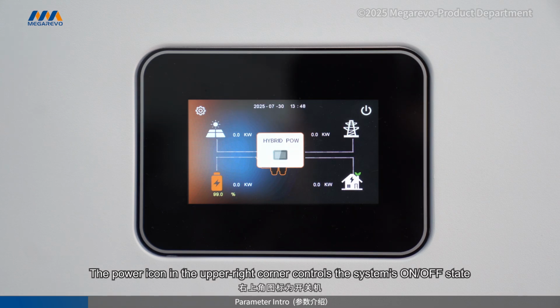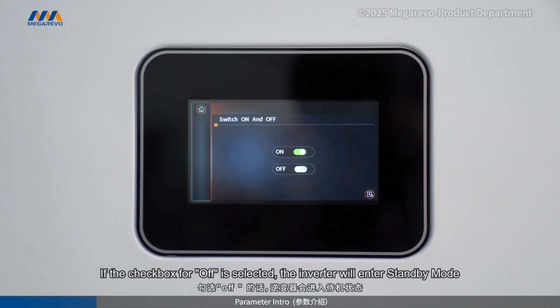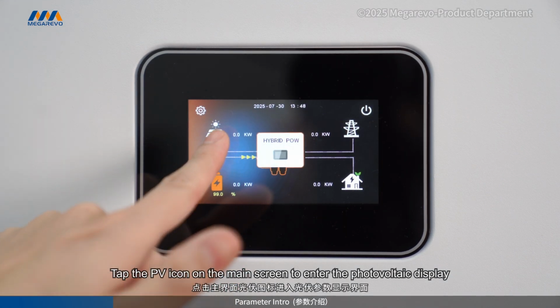The power icon in the upper right corner controls the system's ON/OFF state. If the checkbox for off is selected, the inverter will enter standby mode. Tap the PV icon on the main screen to enter the photovoltaic display.